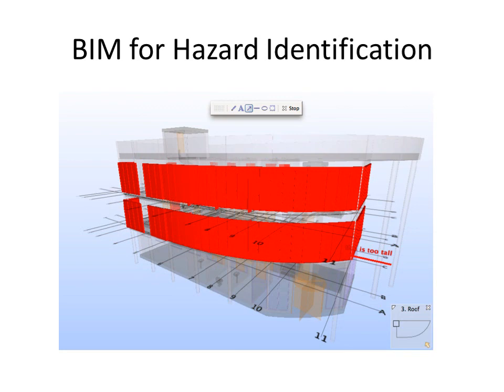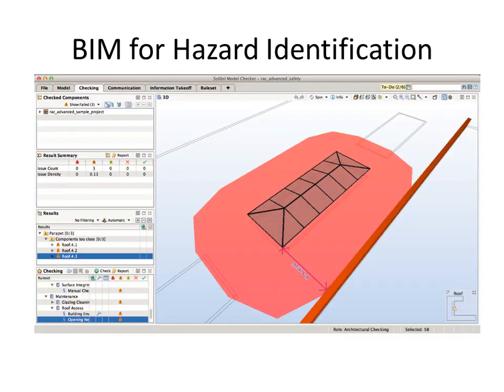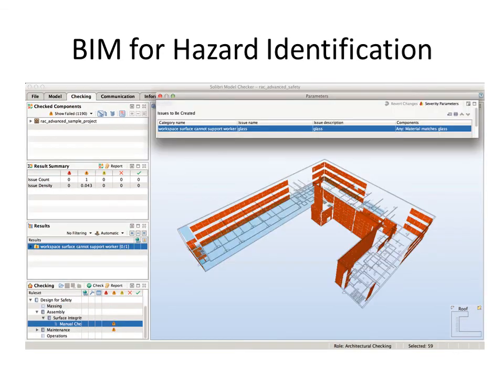Following the findings from the industry survey and from the best practice case studies, specific applications for BIM are being considered. In this example, access issues related to specific systems such as glazing, which check the height for cleaning of this glazing, are being utilized in this BIM application of Solibri. This is another application that checks the two-dimensional distance between skylights and openings. And this is an example that checks particular material properties of glass.